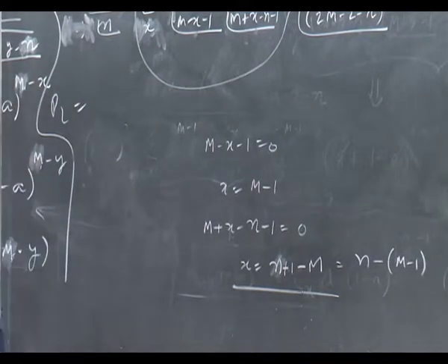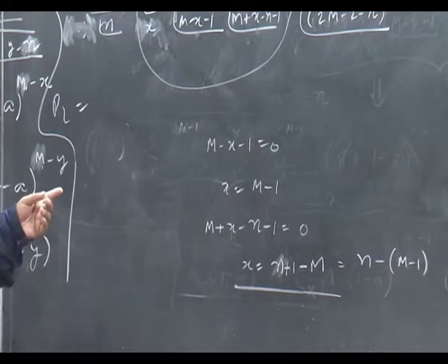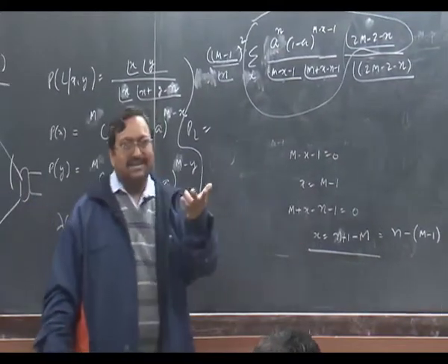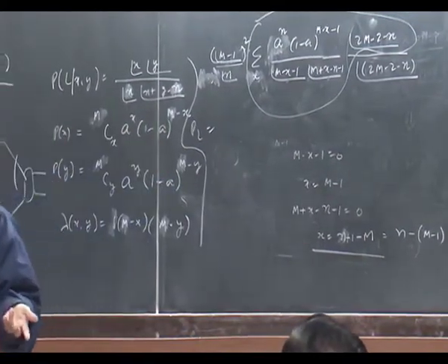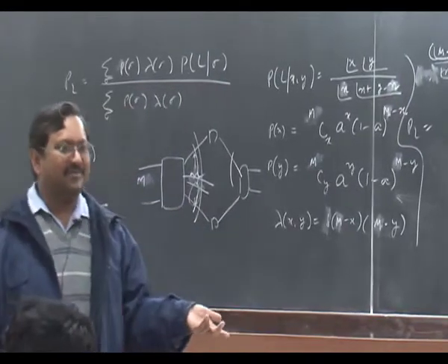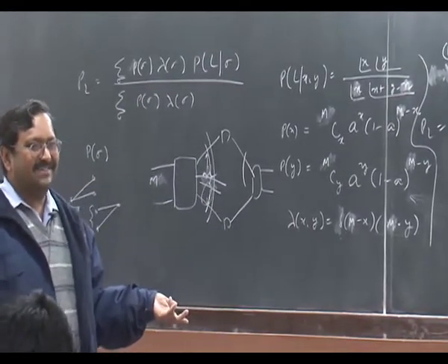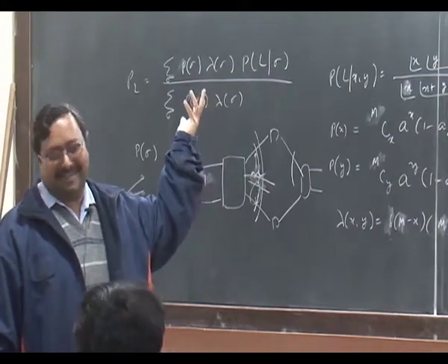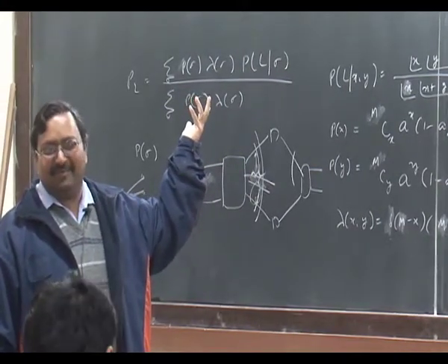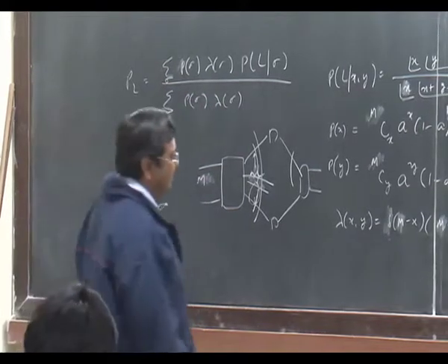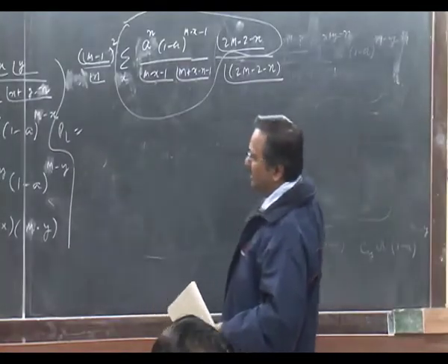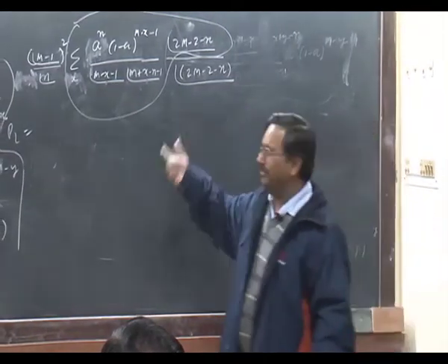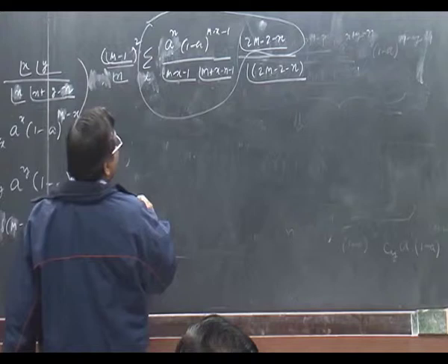And the case which I am taking, when n minus m minus 1 becomes equal to m minus 1, that is a strictly non-blocking switch. In that case, probability of call loss will be 0. The summation, all terms will go out in that case. You will not be including any term. So again, it means I am only taking the values in this range, then it will be a complete binomial, otherwise it will not be. So I can now solve it.